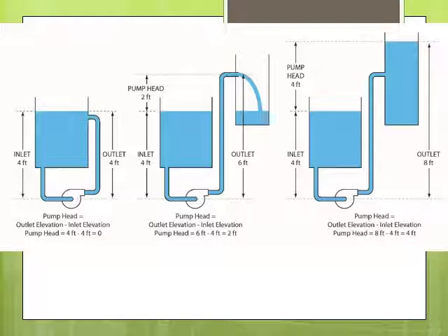So this diagram will help you understand the relationship between lift and height or head pressure. So the pump is represented by this symbol right down here. And in this case, it's just circular. Right? So we have a tank and it's pulling out the bottom, pushing up to the top. Because the water level's above both, there is absolutely no resistance. The water will just as easily go into the pump as it will come out of the pump. So this is going to fling water around rapidly.